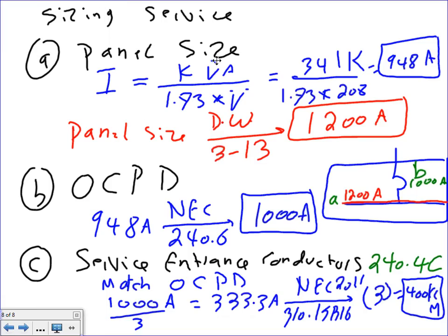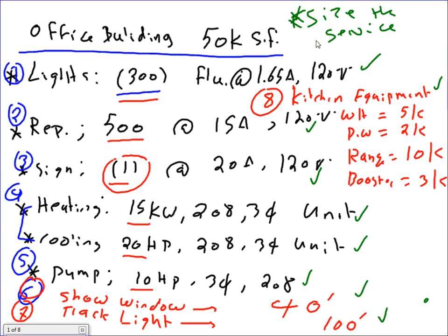All right. Okay, 2 things, guys. Let me go back. So we sized 400 kcm. It's recording, thank you. I'm going to go and size my neutral. The only reason I want to derate my neutral is because of a very important concept: I have a 4,000 amp panel. Otherwise, it's not worth it to go and look at the neutral. It's really not worth it.